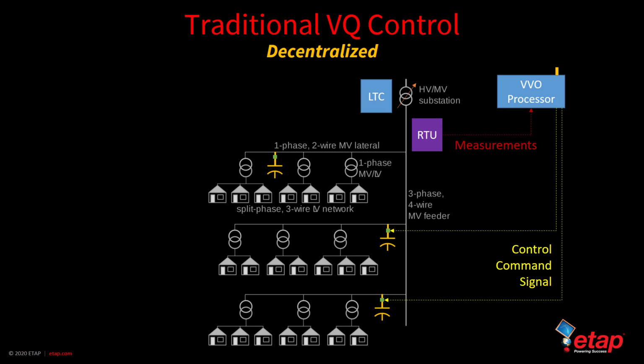These rules are determined in advance by distribution engineers and operators using power flow analysis. The rule-based approach requires a SCADA facility that provides communication coverage to any point on the distribution feeder. This is not a problem for electric utilities that have distribution SCADA facilities. However, adding this facility can be expensive for utilities that do not already have a distribution SCADA.